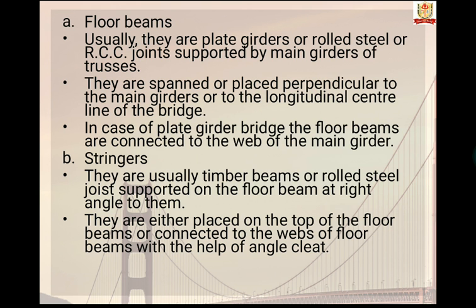Stringers. They are usually timber beams or rolled steel joists supported on the floor beam at right angles to them. They are either placed on the top of the floor beam or connected to the webs of the floor beam with the help of angle cleats.